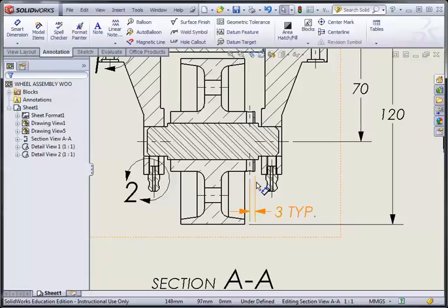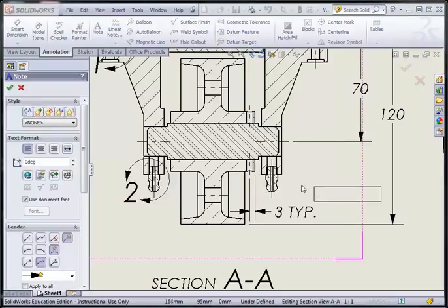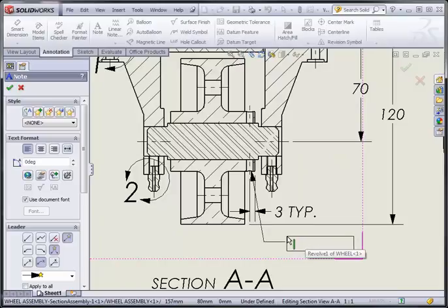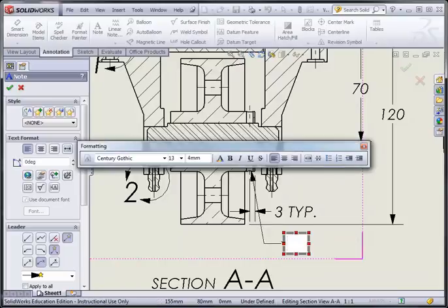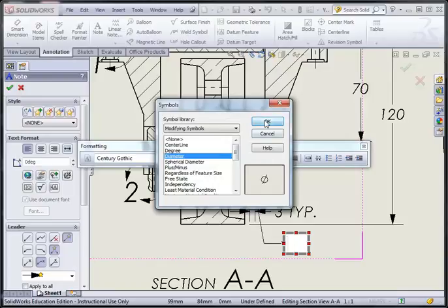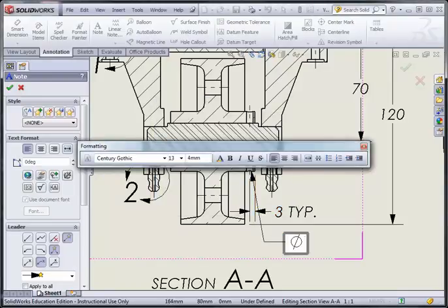You will also notice that there's a note about this hole, so you go under note. It could be a box or it could be pointing out with an arrow, so we will select this edge here, bring that down and enter your note. Now you need a diameter symbol. You can get that under a symbol option here. For diameter, click OK and write down your text. It's supposed to be 4 through to place and so on. You can finish that.